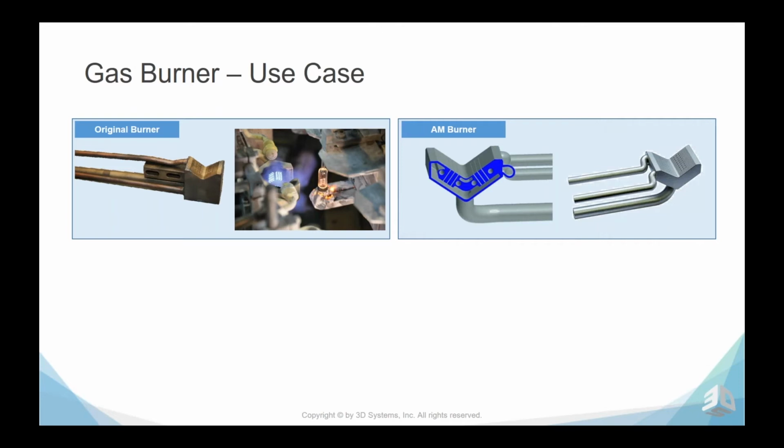So a new geometry was designed with conformal cooling channels that are less than 1 millimeter away from the burning gas. Now, the results were, first of all, we achieved the main incentive for the new design, which means the lifetime of the part was tripled.